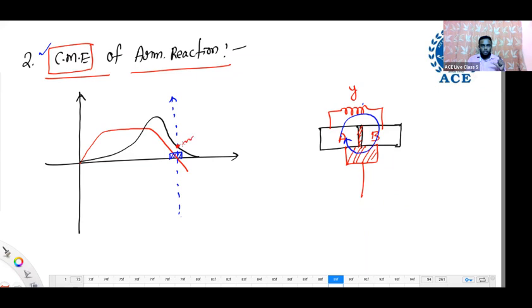Now, when there is a small amount of flux, what is this flux? Main flux. That is time invariant flux. Due to this flux, an EMF is still induced in the coil. What is that EMF? Dynamically induced EMF. Previously, there is reactance voltage. Now, additionally, this EMF is also there. So in the coil, already there is reactance voltage plus an additional EMF due to the cross magnetizing effect.